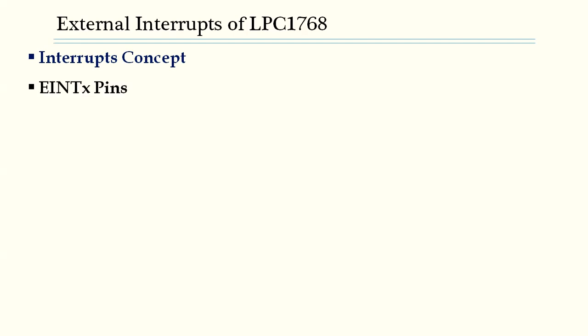Now, with the LPC1768 we have the EINTx pins. That means there are external interrupt pins 0, 1, 2 and 3. If you recollect the pin configuration of LPC1768, we have EINT0, 1, 2 and 3 as the external interrupt pins.